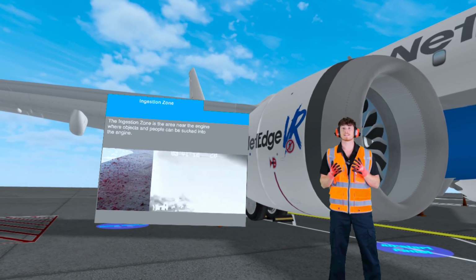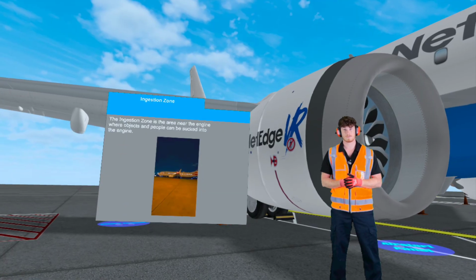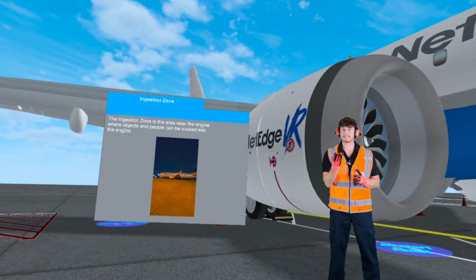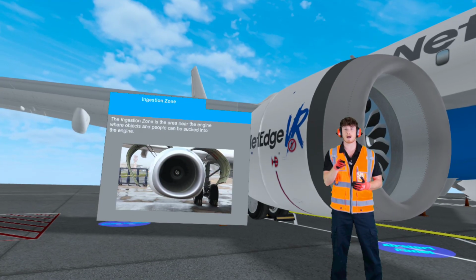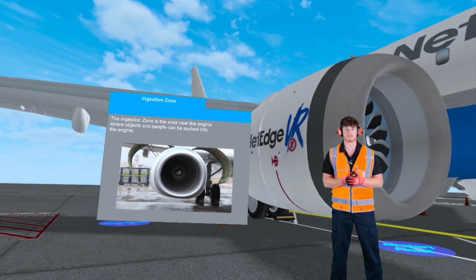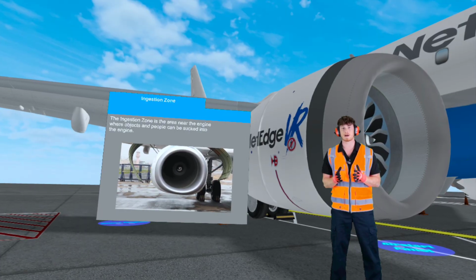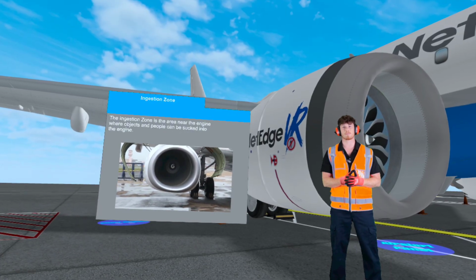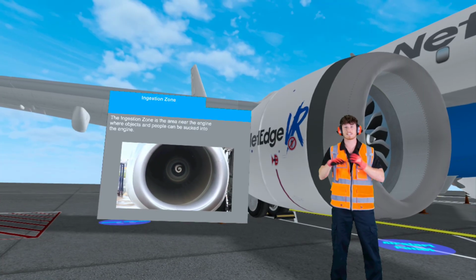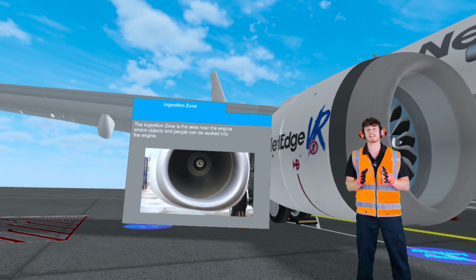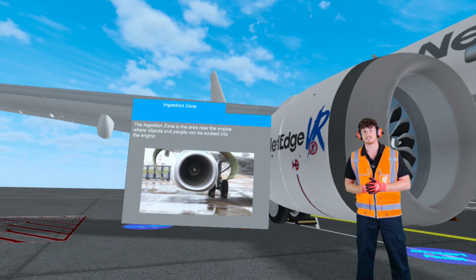So, how do you know when it's safe to approach an aircraft? Well, first, check that the beacon light is off. Then, your main indication is this spiral pattern in the center of the blades. If you can clearly see the spiral, it is spooled down enough for you to approach. If you can't see the spiral and you just see a messy blur, then the engine still has powerful intake and it can ingest you.